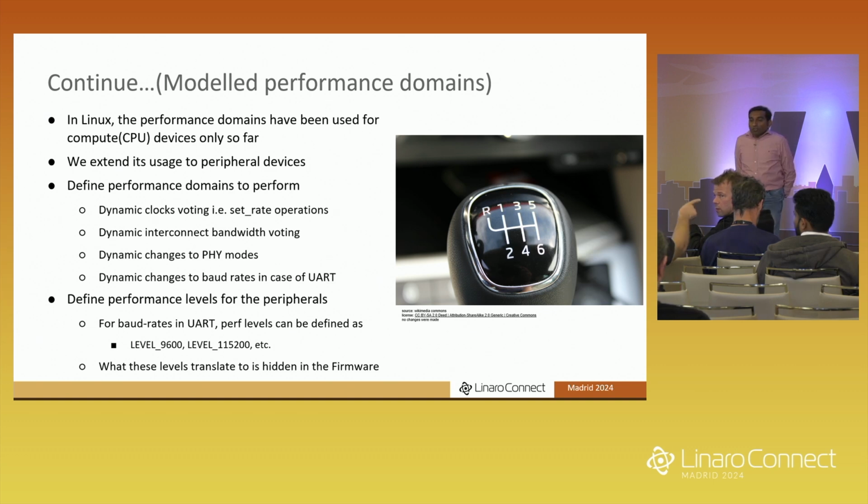Yeah, but in this case, for example, if we take the UART level 9600, the baud rate, how do you reflect that? That's really what we want. It doesn't necessarily have to be a clock value, right? It's a frequency value, the way you see it. That's the UART baud rate, but that doesn't mean what will be the system clock of your IP, or what frequency you can have.